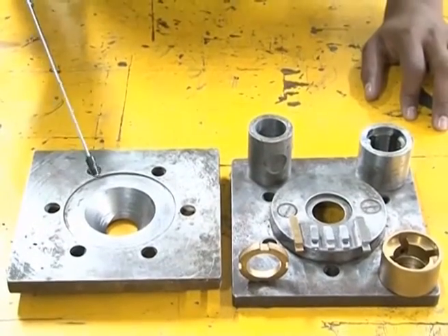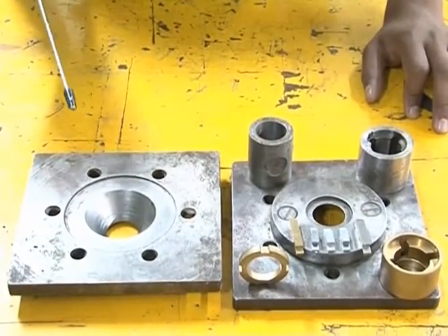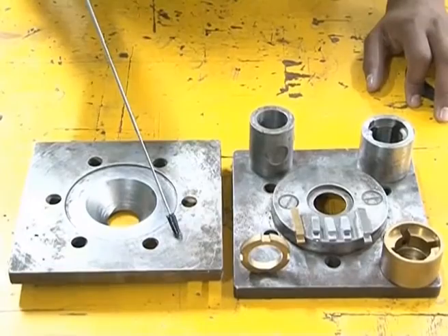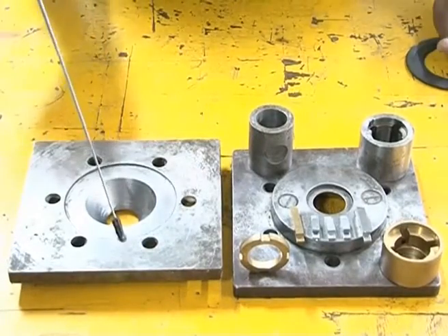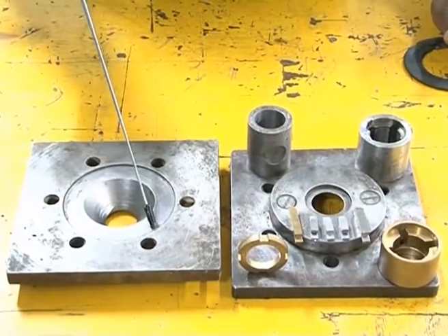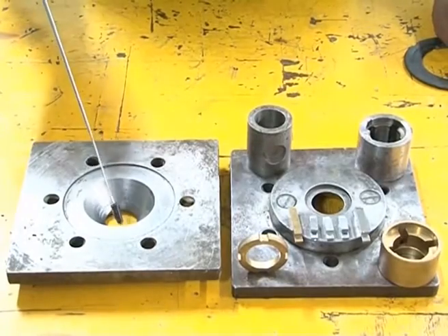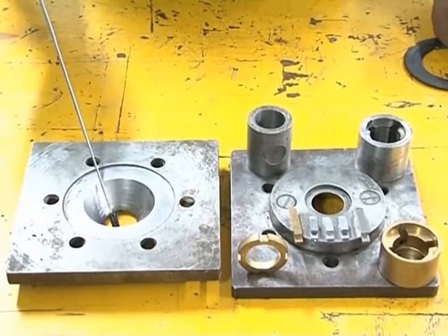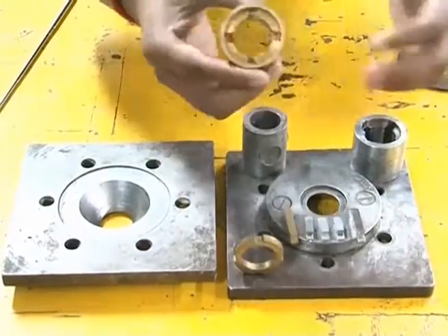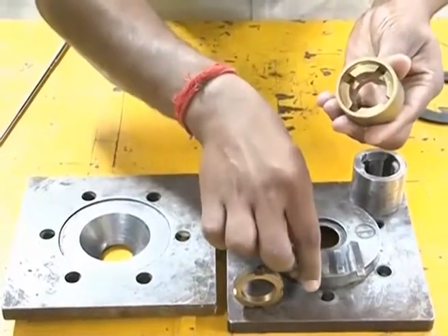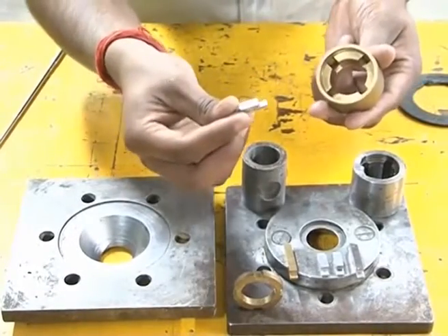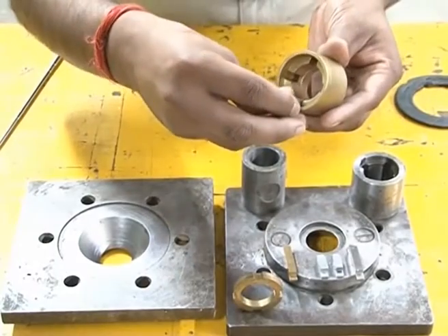Tooling controls the flow of the medium in the place where it is required. So this is the bottom plate and this is the top plate, and this diameter is equivalent to the lower medium cylinder size, and we have a taper portion to control the medium gradually into the working region. And this is the work fixture where you can fix the workpieces. These are the workpieces, and you can fix them like this.